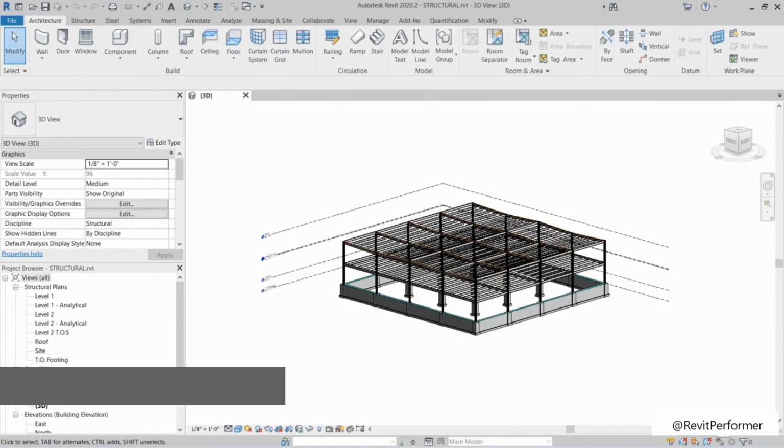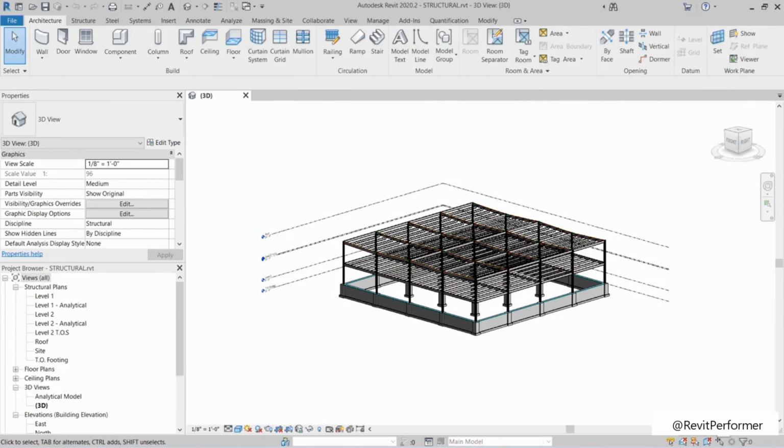Okay, this should be easy. Here, I'd like to add a second floor as well as roof decking. We're going to cantilever the concrete 8 inches beyond the framing center line. Then we need to snap the roof deck to our framing.